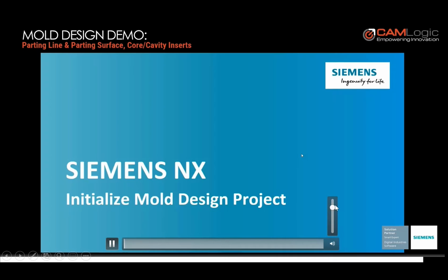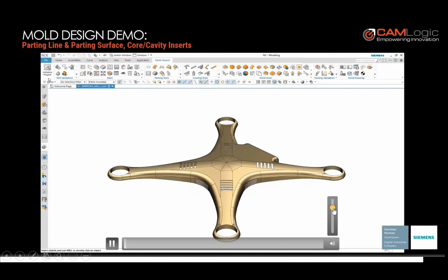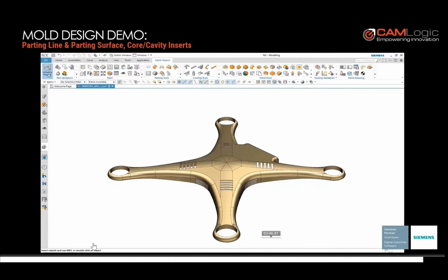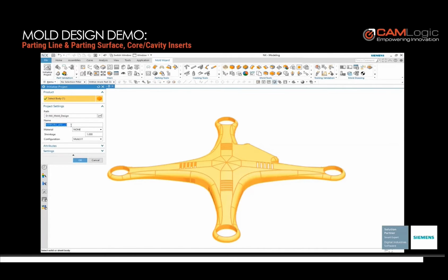Once the part has been validated by the tool designer, the next step is to create the mold tool design. To start, you need to create an assembly structure for your new mold design. Using conventional CAD systems can be tedious and time-consuming. By using a single command in the NX Mold Wizard, the system will automatically clone an empty assembly structure for you.